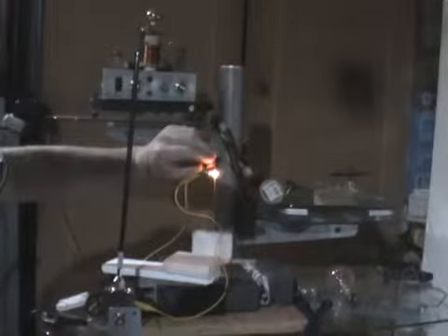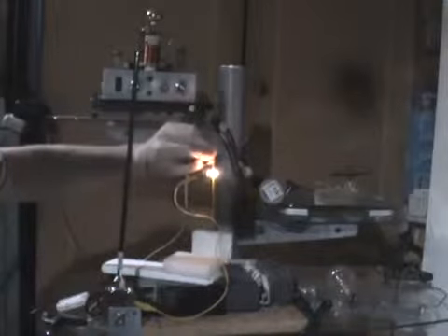But wait, I may be acting as an untuned antenna and detuning the area when I bring my hand close, so I will actually earth it with an earth connection, and it also decreases in brightness. Now, I earth both ends and it still remains illuminated. By the way, interestingly, it is actually brighter without the other dipole when placed at the same distance.